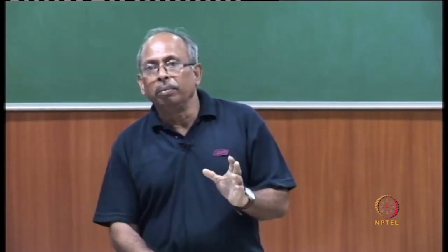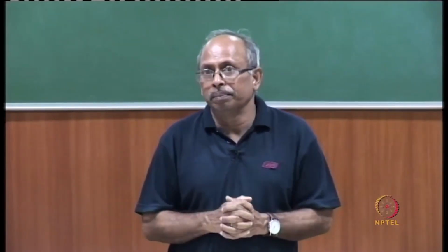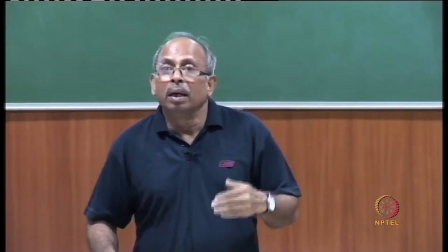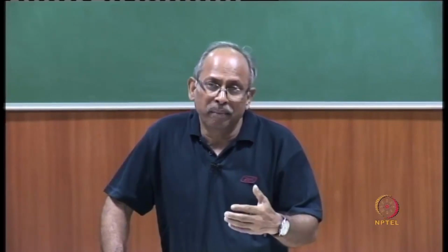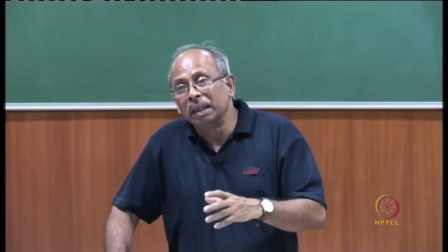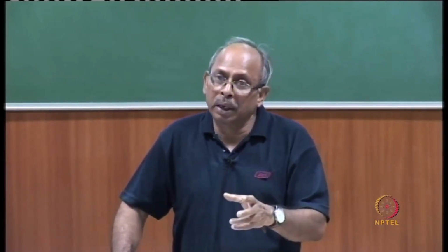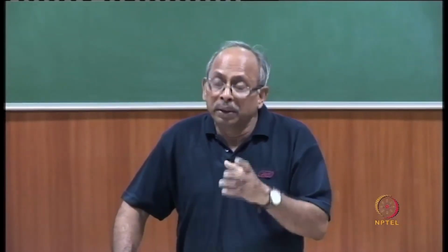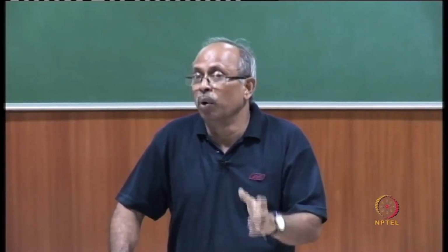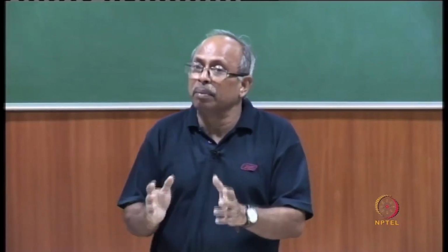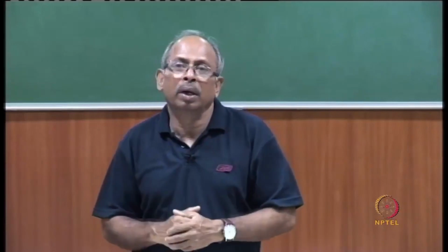So you can summarize now. Basically, we have looked into all the methods of compaction, and the mechanism of how compaction occurs. And lastly, we looked into curing: the methods of curing, need for curing, and importance of curing. One thing is that curing is very important for durability, which people quite often ignore. It's good for strength development, but minimum curing is absolutely essential for durability.